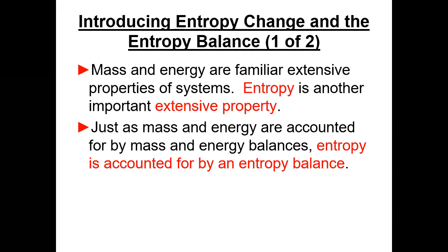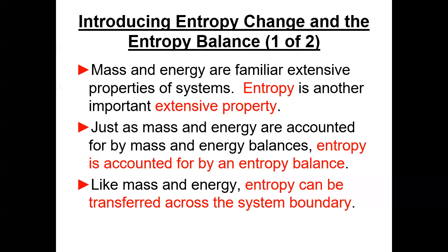And we will, just as we have done mass and energy balances, and done calculations based on the balance, we will have an entropy balance as well. So it follows along. It's not exactly the same because entropy is a little bit of a different beast, but we'll see that as we go through here. And so like mass and energy, entropy can be transferred across a system boundary.